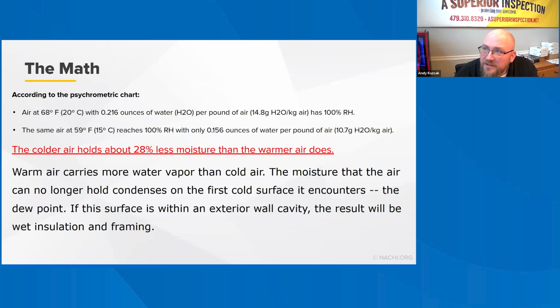In addition to air movement, one can also control temperature and moisture content. Since insulation reduces heat transfer or flow, it also moderates the effect of temperature across the building envelope cavity. In most US climates, properly installed vapor diffusion retarders can be used to reduce the amount of moisture transfer. Except in deliberately ventilated spaces such as attics, insulation and vapor diffusion retarders work together to reduce the opportunity for condensation to form in a house's ceilings, walls, and floors.